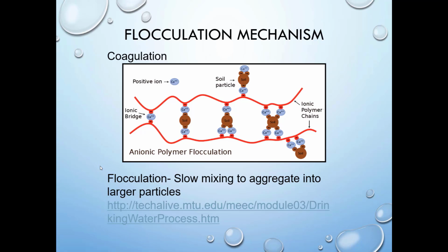All right, so that's flocculation and coagulation. We haven't talked about the disadvantages of flocculation and coagulation. Really the main disadvantage here is that this anionic polymer, and really any polymer, is prone to breaking down and releasing units of the monomer back. And the issue with any polymer releasing its monomers is that the monomers tend to be toxic.